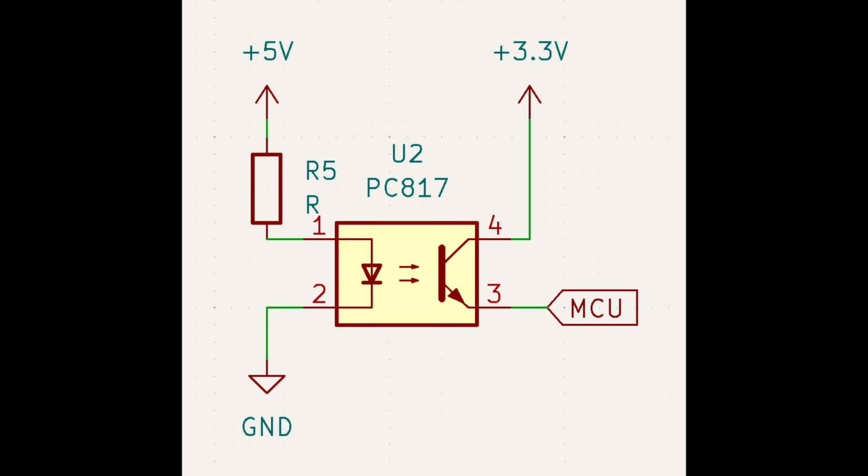Now, let's look at an application circuit. The 5V at the input passes through a current limiting resistor and is delivered to the photocoupler's input. At this time, the IR LED activates. Light from the IR LED is transmitted to the phototransistor in the output section. The phototransistor activates, allowing current flow in the output section. This is how the photocoupler performs its role in a circuit.